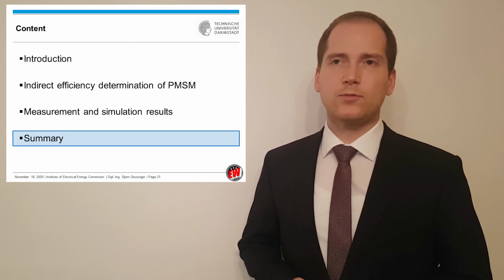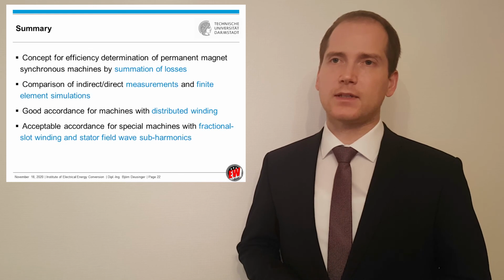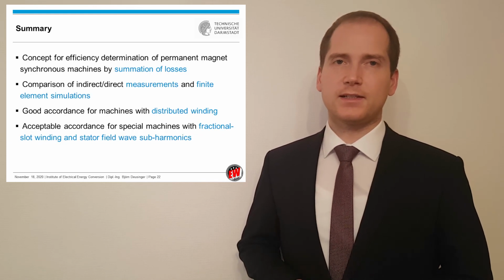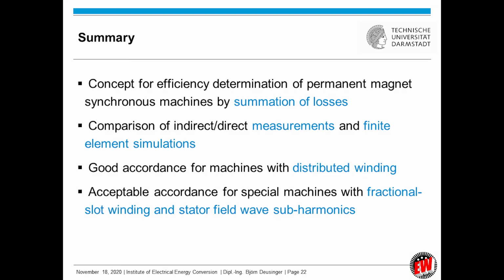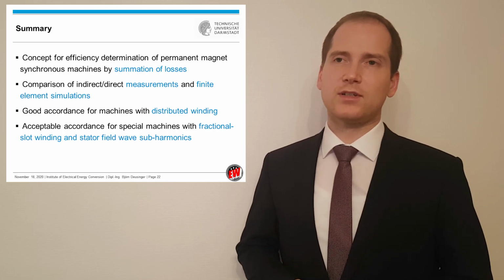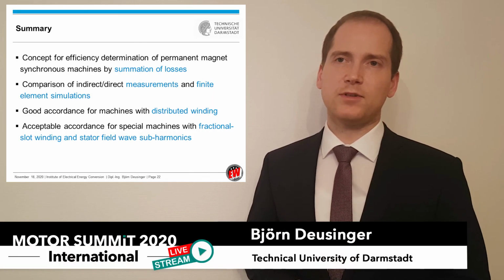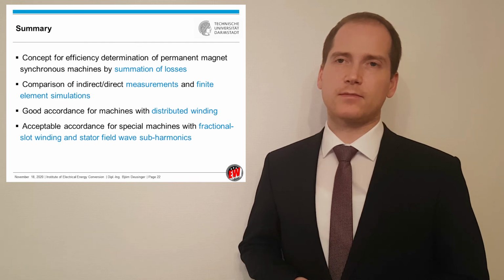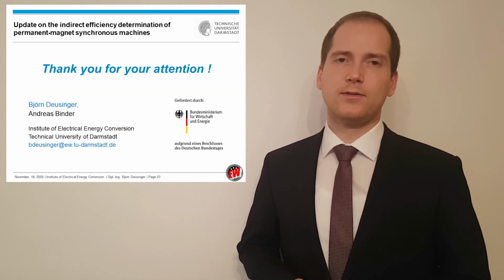So finally we come to the summary. I presented an alternative concept for indirect efficiency determination of permanent magnet synchronous machines, which has been evaluated by measurement and simulation and is now at a review stage for inclusion into the IEC standard. We saw a good accordance for machines with distributed winding and an acceptable accordance for special machines with fractional slot winding. So, thank you for your attention.